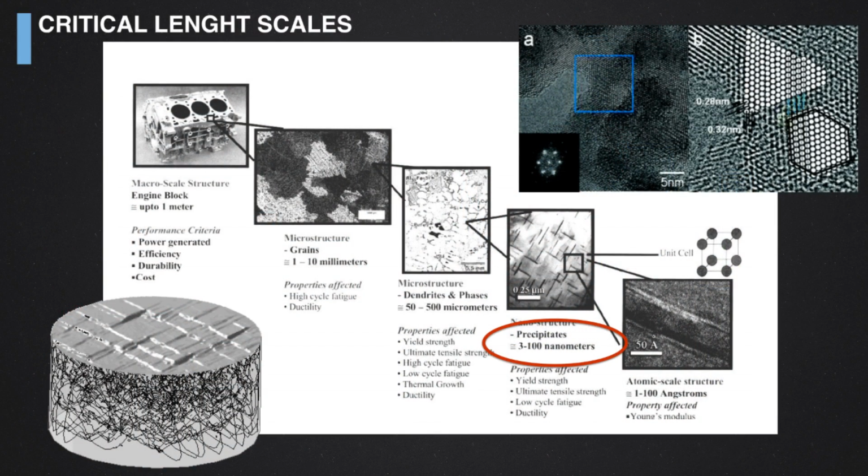From that point, some dislocations, some movements of the atoms will be generated when you submit the material to a mechanical stress. And you can actually see them through the transmission electron microscope as black parts where the atoms are disordered. And you can keep deforming the material and submitting it to a mechanical stress until the density of those defects is high enough to make it so brittle that it breaks.